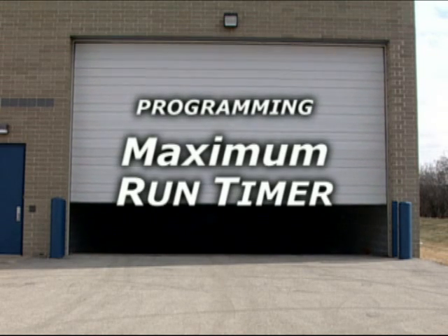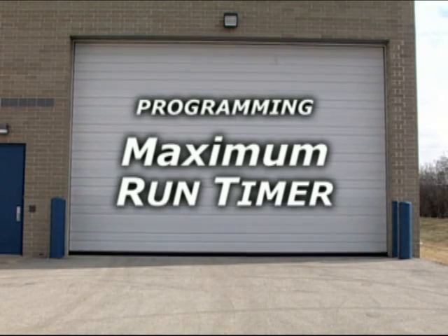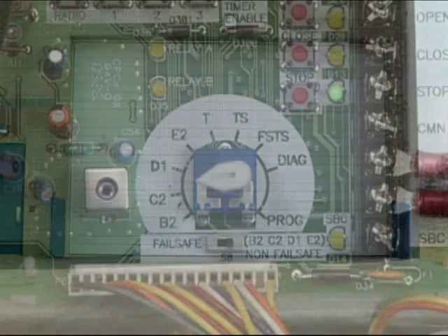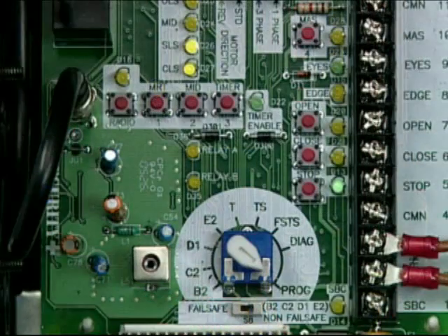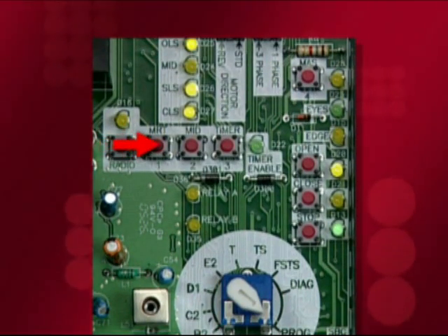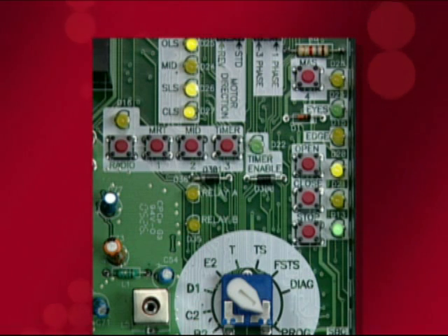We will now review the programming steps in setting up the maximum run timer feature. Begin with the door in the fully closed position. Turn the selector dial on the logic board to Program. Press and release the MRT button on the logic board. The Open LED and the OLS LED will blink continually.